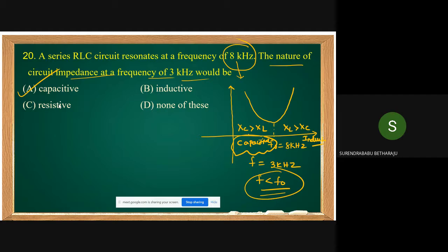In this question, for 3 kHz frequency, does the current lag the voltage or lead the voltage? The circuit is capacitive. What about the current, lagging or leading? The current leads the voltage. Yes, friends, current leads the voltage.